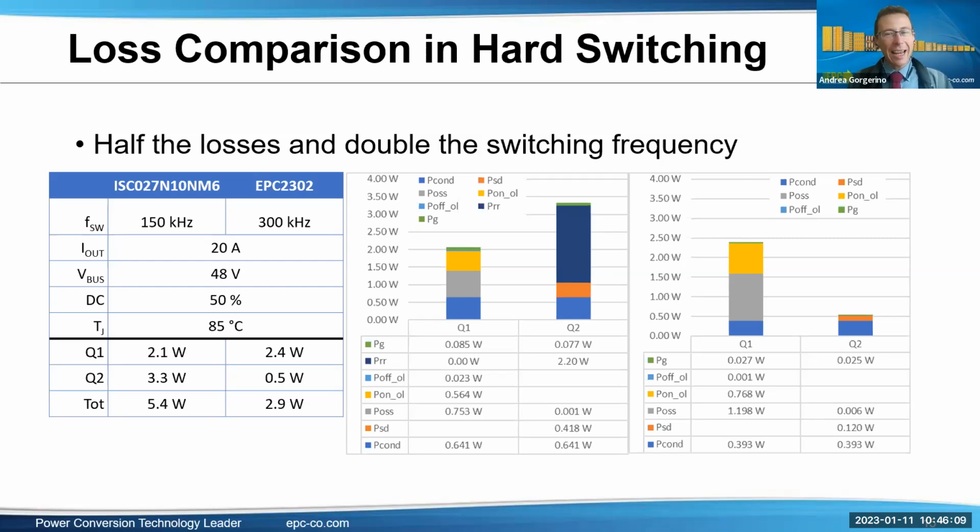All I can say is similar behavior for RDS(on) as a silicon FET. It depends on the part. The temperature coefficient is slightly different for RDS(on), but usually slightly lower, but very similar. The threshold also has a temperature coefficient. Silicon FETs have quite negative temperature coefficient, which means it gets lower with higher temperature. GaN FETs have much more stable threshold, so it's almost constant over temperature, which is a better behavior, I would say. But that's all I can say. I'm not sure I fully understand the question.